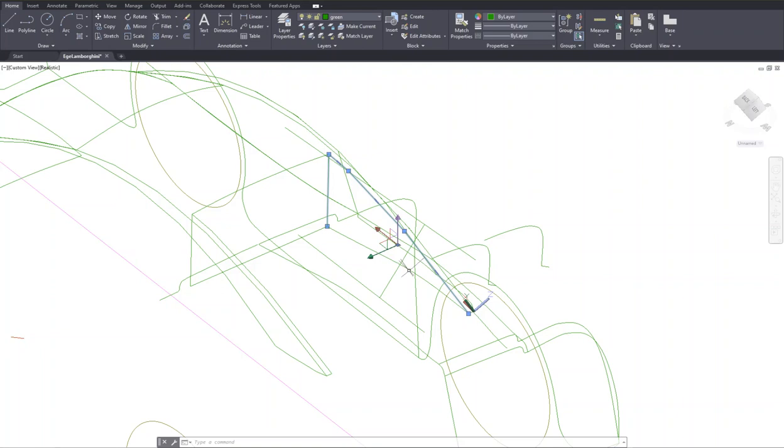But the good thing is I realized that it's not going to work, so I divided, I broke a line into 2 small pieces. Now we have 4 lines, and that will enable us to use the edge surf command.